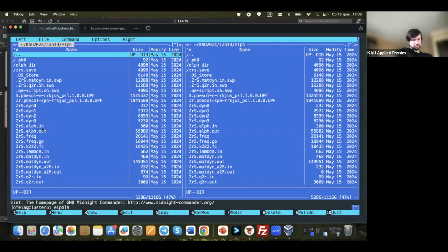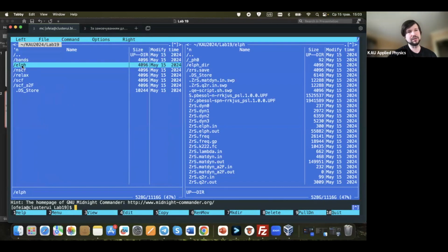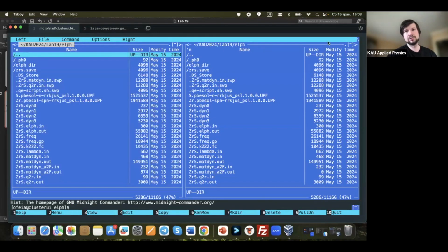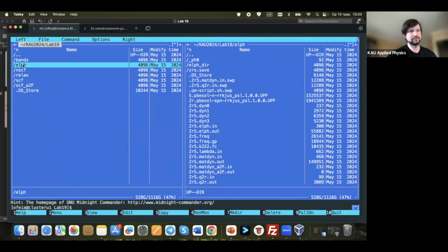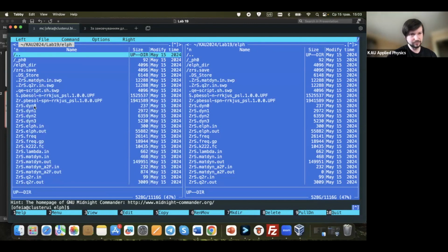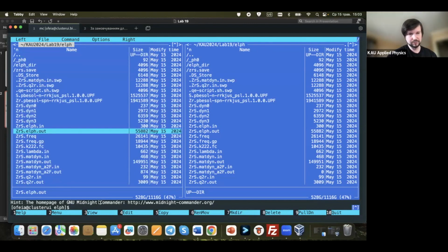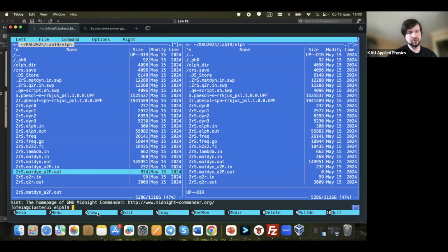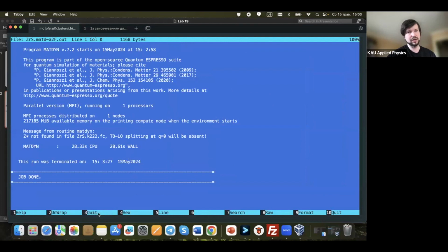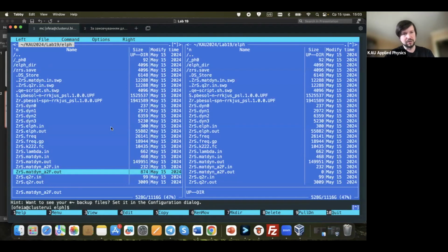Probably we can try to plot this Eliashberg function, but I suggest that we go directly to lambda, and just do it as an intermediate step, because from minute to minute they will take our Zoom. So it's like matdyn A2F out. Yeah, should be okay. And now lambda.